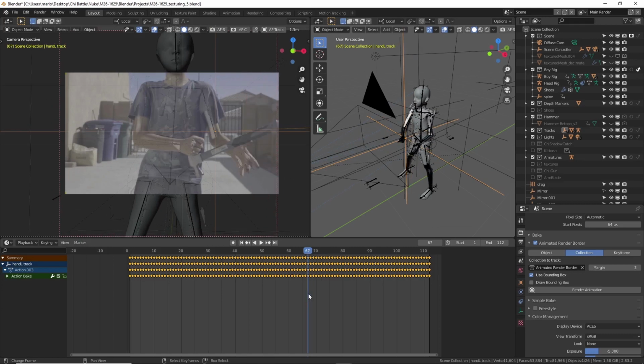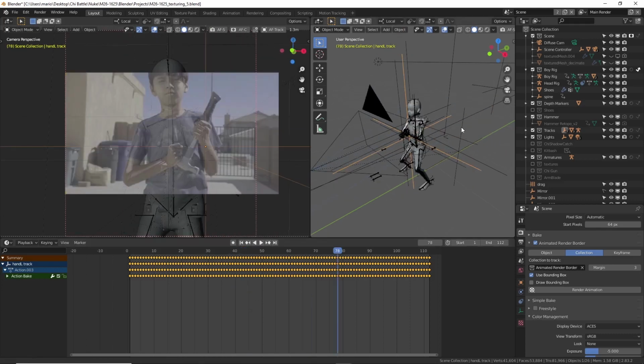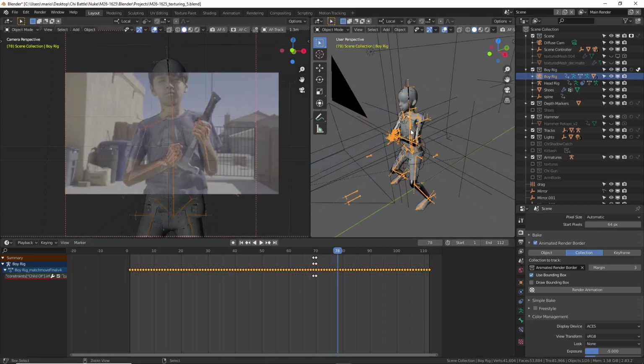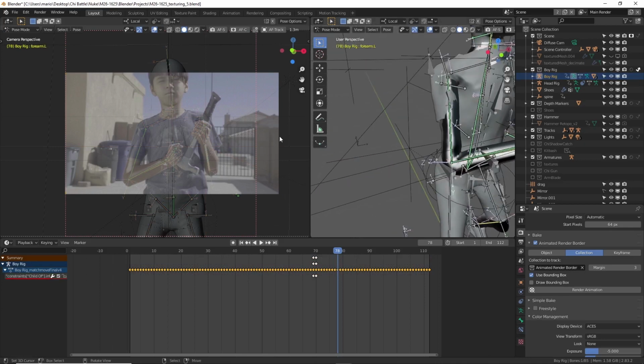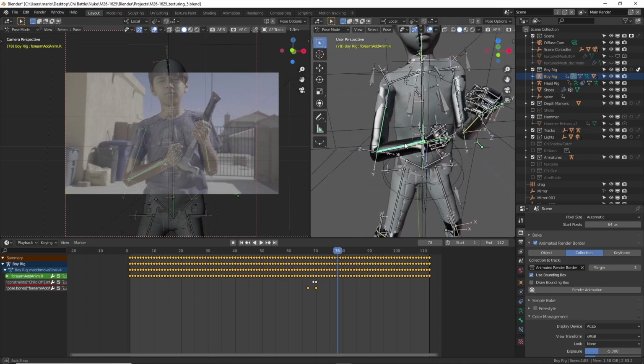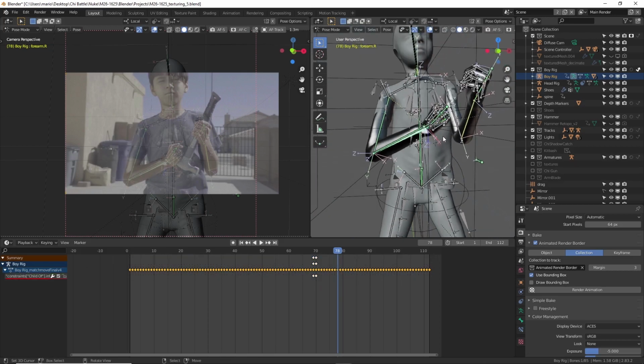But I wanted to have the same animation with a little bit of offset, and so I had to use all kinds of constraints and whatnot. That's why there's multiple bones in here. There are duplicate bones. I don't think you can see them because, oh yeah, see right here, even for the arm, there's duplicates so that I could add more rotation and more offset.